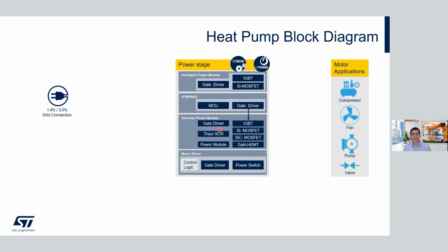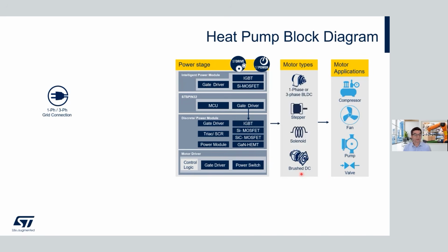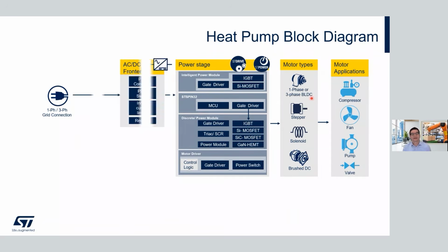With these power stages, we are able to drive these different kinds of motor applications, which can be found inside a heat pump application. Those motor applications can be driven by either BLDC motors or steppers or solenoids or whatever, depending on their exact needs. We will focus in this application reference design mainly on 3-phase BLDC motors. And on the AC front end side, as we said in the beginning, we have an active PFC solution. Normally, in order to fulfill the legislations for the